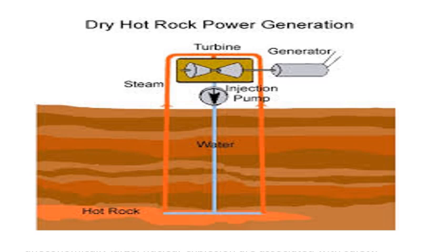We are going to inject the water, and because the rock is very hot, the water, when it comes out, is in the form of steam, and from this steam we are going to run the steam turbine. And once the steam turbine runs, surely it has to be coupled with the alternator, and after working it will be cooled down and once again injected.